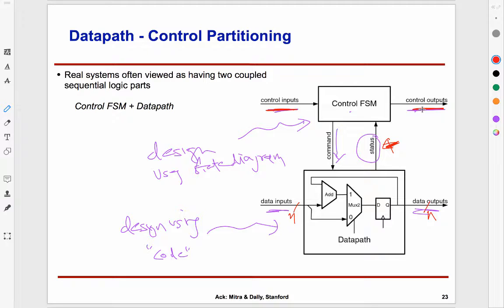But each press of the key that I may do on the keyboard, that corresponds to, if you just think about it, my clock is nanoseconds, my key presses are milliseconds, you're looking at 6 orders of magnitude, so I can have millions of clock cycles in a single key press. So now think from a state machine perspective. What's happening is each time I press the key, it's not as if you are seeing that key press just for one clock tick.